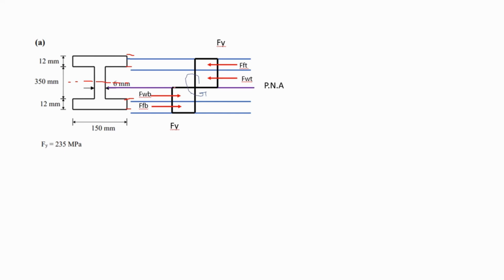Now, another thing we have to consider is that the section reached the plastic region in the stress diagram. Therefore, the stress diagram, as we can see here, is taking this shape as rectangles. This can be considered as tension. This part is tension completely, and it changes at the plastic neutral axis, reaching 0 here, and this becomes compression.